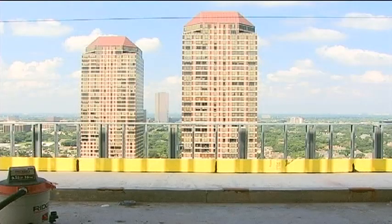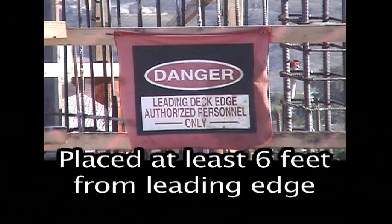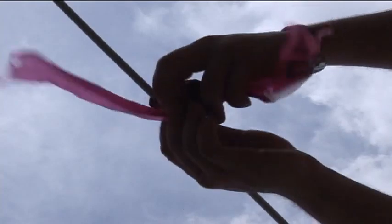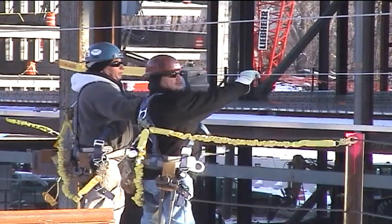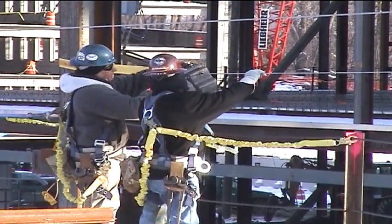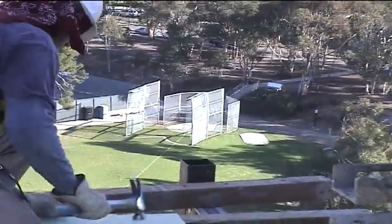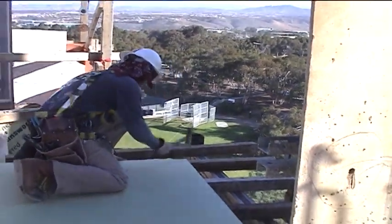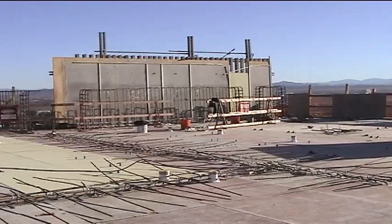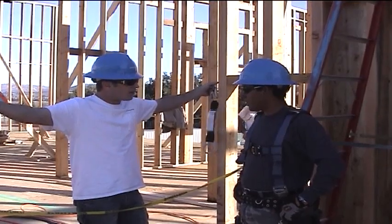The barrier is a warning line consisting of rope, wire, or chains placed at least 6 feet from the leading edge and flagged at 6-foot intervals with high visibility material. Employees are not allowed between the roof edge and warning line unless performing roof work. Employees performing roofing work between the roof edge and warning line must also be protected by guardrails, nets, PFAS, or a safety monitoring system.